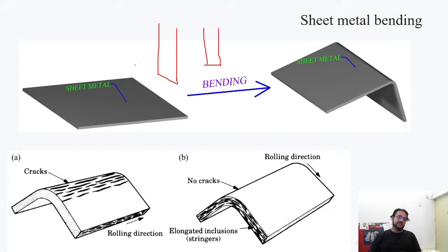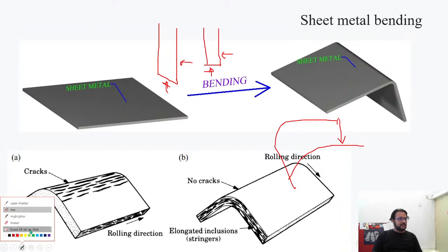So it depends. Sometimes when it is a material which is very much ductile, there are chances that this kind of rollover portions in the cutting surfaces are going to be very large, right? So if this is how the material may get cut because of its larger ductility properties and all of that, then you do use something like this. However, there are punches like this also. For smaller ones you can go with this. For much larger ones, I think these are more suitable, something like that. I hope that answers Gaurav's question.